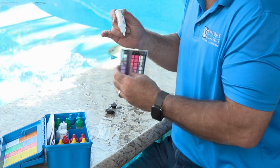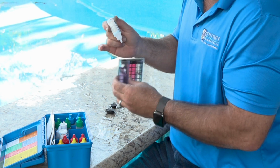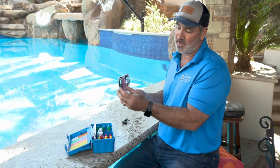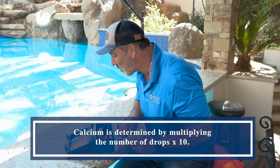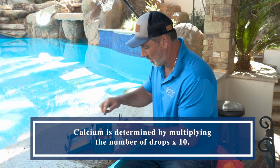It's kind of a purple color now. And like I said, between pink and blue, you get purple. So mine's changing somewhere around 38 to 40 drops or so. So multiply that times 10 per my instructions, and my calcium hardness is about 400. So 40 times 10.